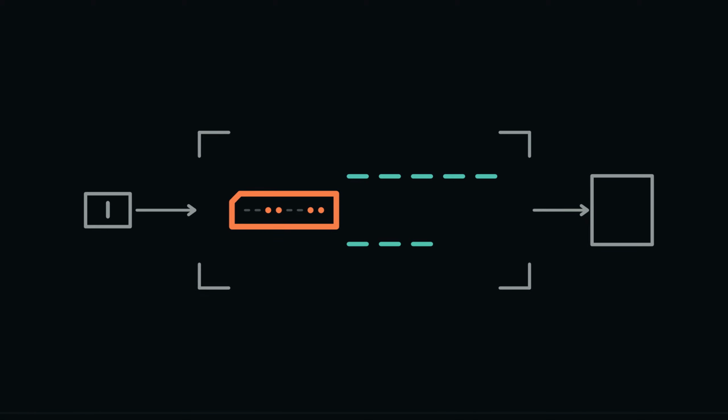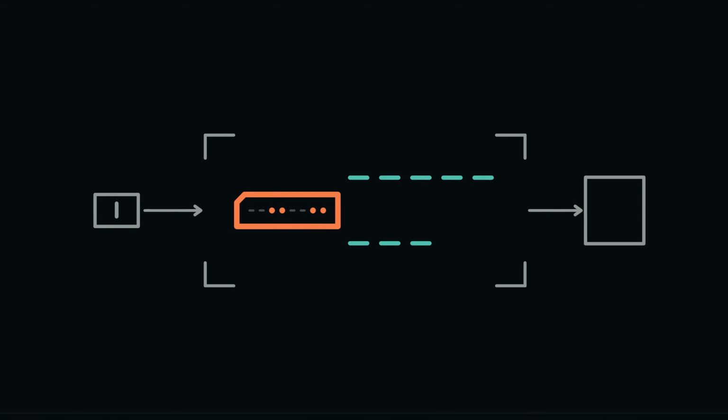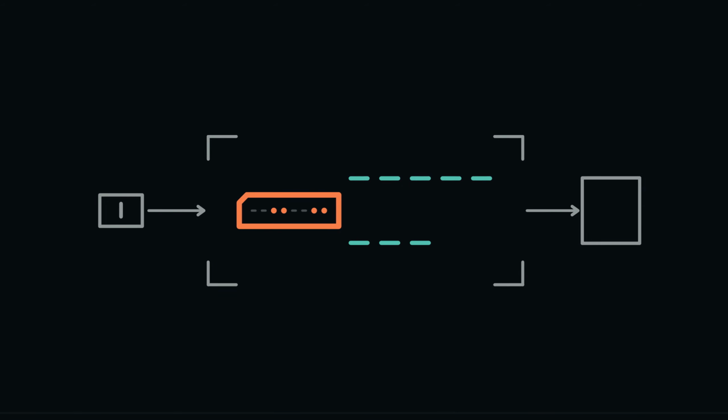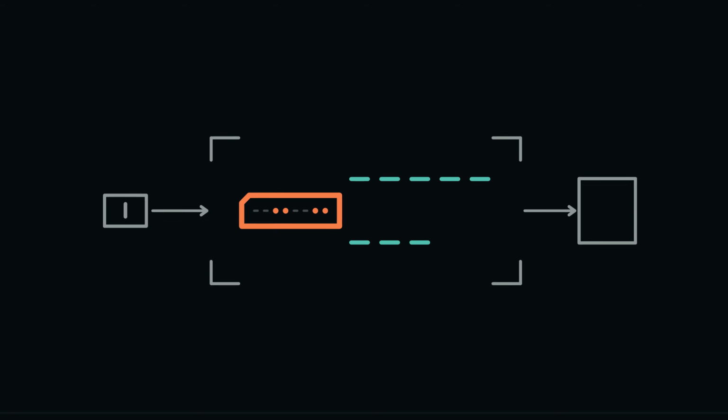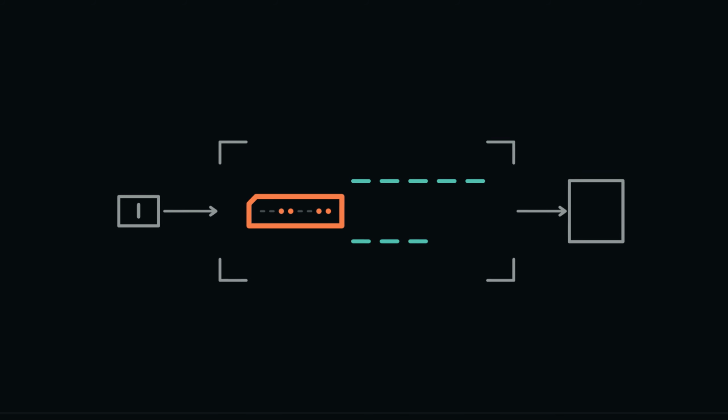Recognition is not enough. A trace can feel obvious after every answer has been highlighted. So here's a related program the film has not run for you. It begins at address hexadecimal 20 with a value already in R0. It subtracts 1, compares the result with 0, branches to the end if the 0 flag is set, and otherwise jumps back to subtract again.